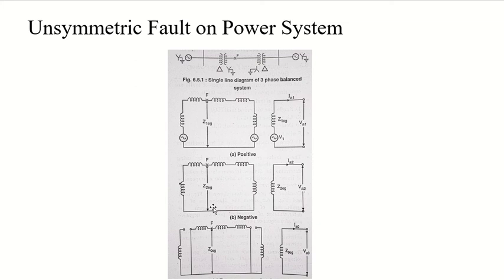And this Thevenin's equivalent for negative and zeroth can also be obtained from the negative and zeroth sequence component of my power system. A small detail I want you to notice is this one. For zeroth sequence component, these two are short circuited here. So I want you to tell me what can be the reason for this.